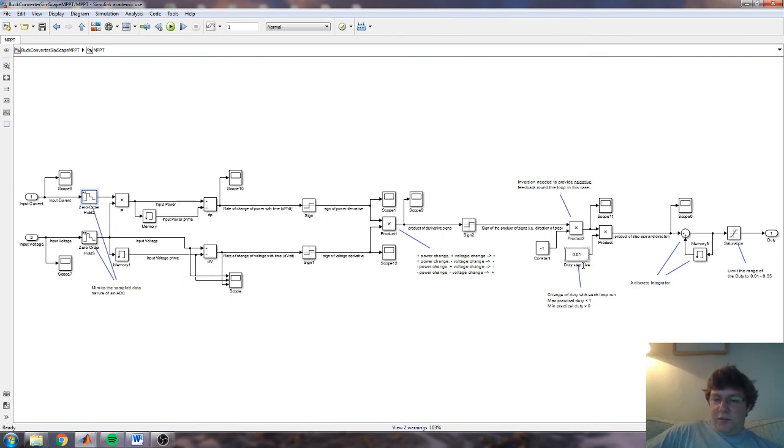So this is the step size we'll take, and if you make this bigger, of course you'll take bigger steps, and in control system terms, your phase margin in your control loop will be lower because your gain around the loop's bigger, and that obviously leads to a faster response time but a greater chance of instability. And if you make this small, you will have a slower response time but the likelihood of more stability.